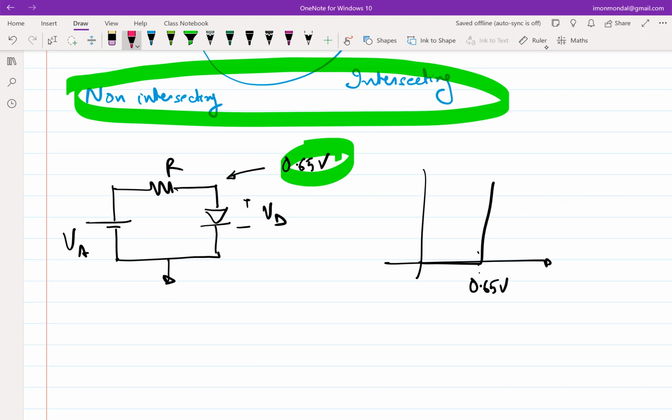Right. So what he is essentially pointing out is that if I plot my diode characteristics and I know that this is exponential, it will look like this. So maybe I can say that it's simply because dealing with exponentials in transcendental form is difficult, so I'll just say it's a kind of sharp rise at 0.65. But the point I'm trying to get at is that there is nothing sacrosanct about this 0.65. It's exponential throughout, right? So why am I setting that threshold point at 0.65?